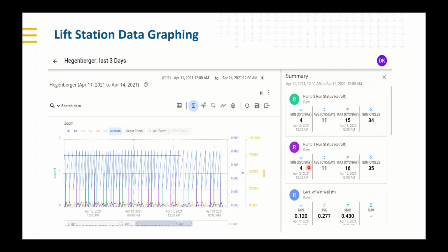And what you can also do with that is track the pump health and the activity. There are different ways to identify all 3 of your pumps at the same time. And then you can get all the run times and compare them to each other and see which pumps may be running inefficiently, which pumps may be about to fail. So you can really get a good visual of what's happening in your system to allow you to be proactive.